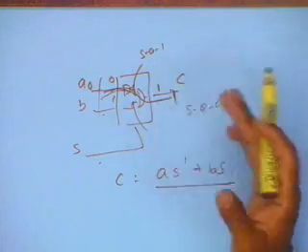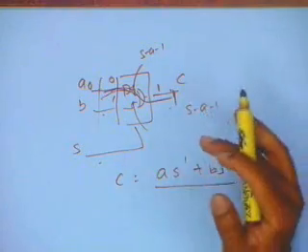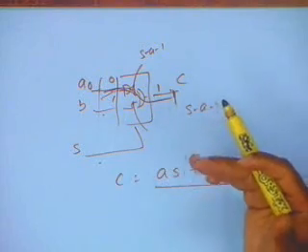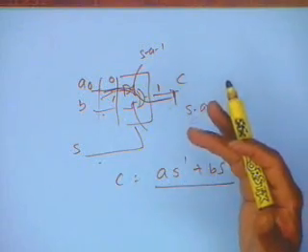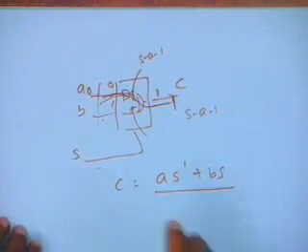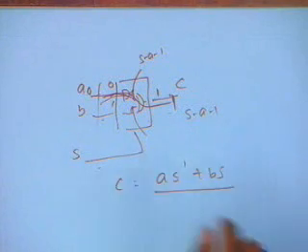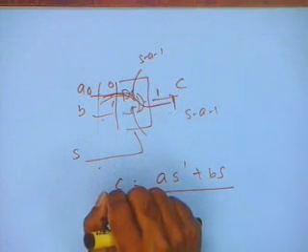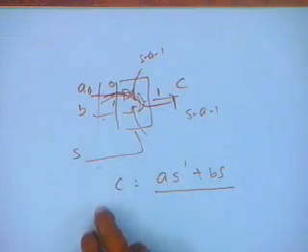So it is possible to do that, but my actual fault coverage will obviously go down, but the number of test vectors that I will require will also drastically come down, because I have fewer nodes now to bother about. And this particular approach you can apply not only to fault simulation, you can also apply to deductive fault simulation, because as long as I can formulate those equations, the equations were this union, intersection and complement, if I can understand how these faults are getting propagated, and those equations are very simple to formulate.